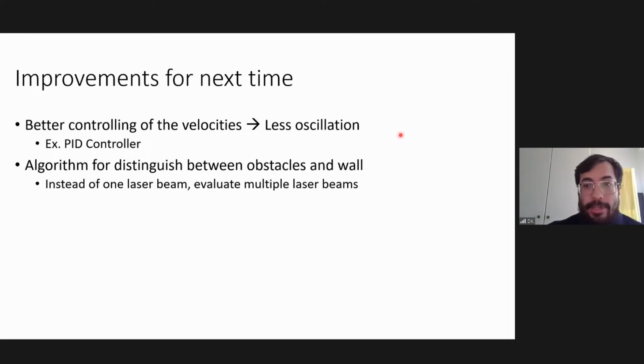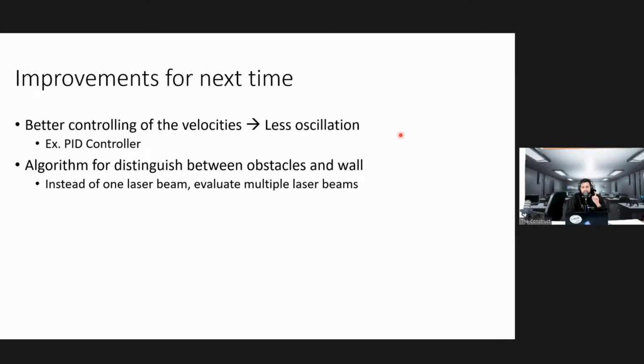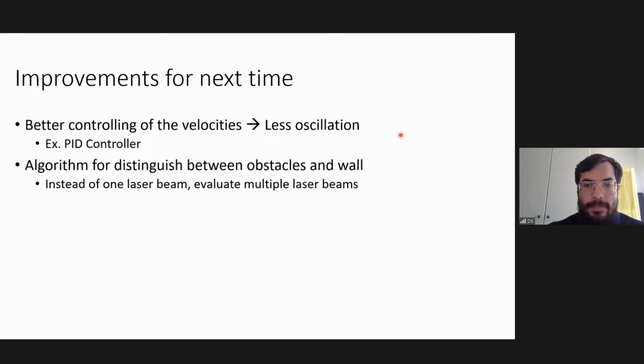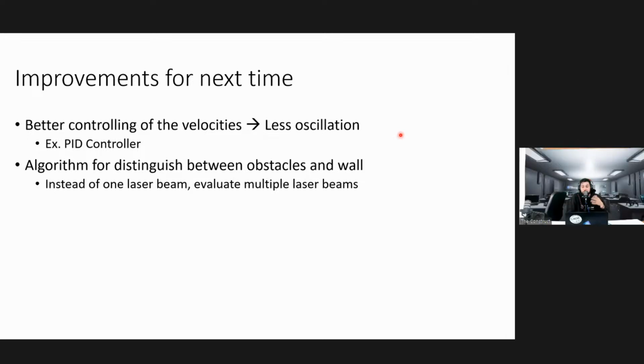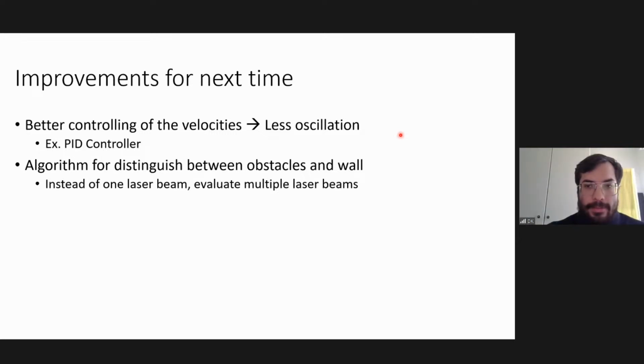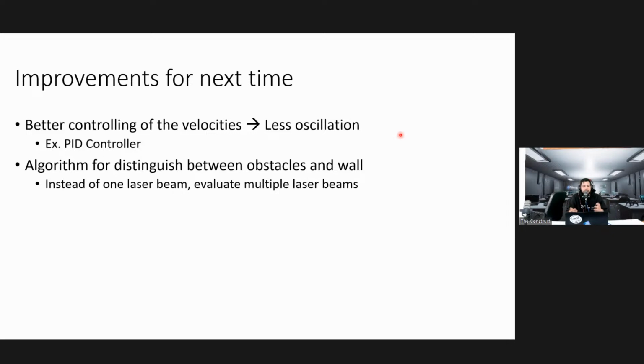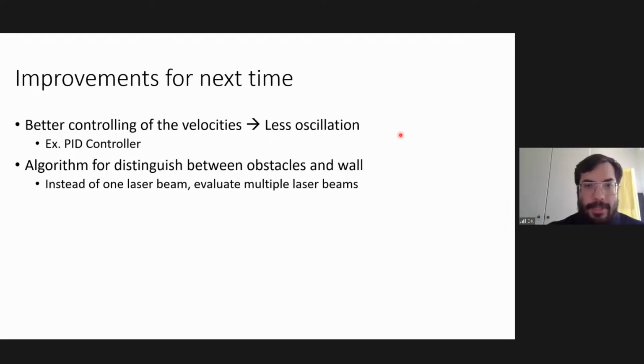So the odometry you can use to know where you actually are in the room. You can also use this data to locate yourself, and then also drive depending on where your actual position is. I don't know if you know this, but the odometry from wheel encoders on robots always has a drift. As you go on, it will have an error. So you can also match it with the scan and see how big that drift is. Nice. I just wanted to see if you had thought of something.